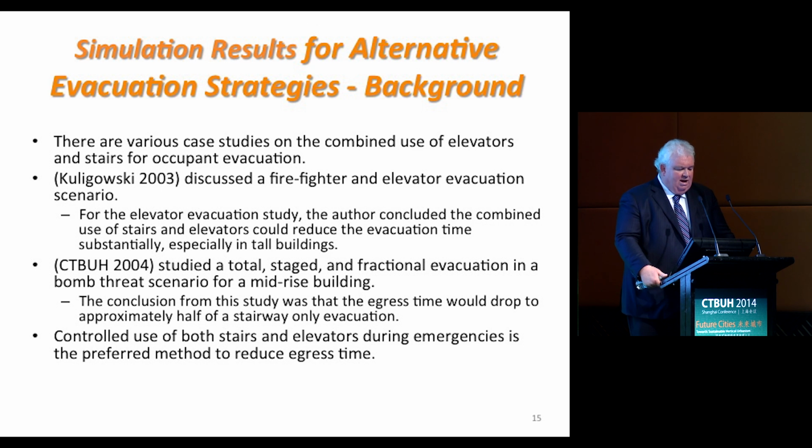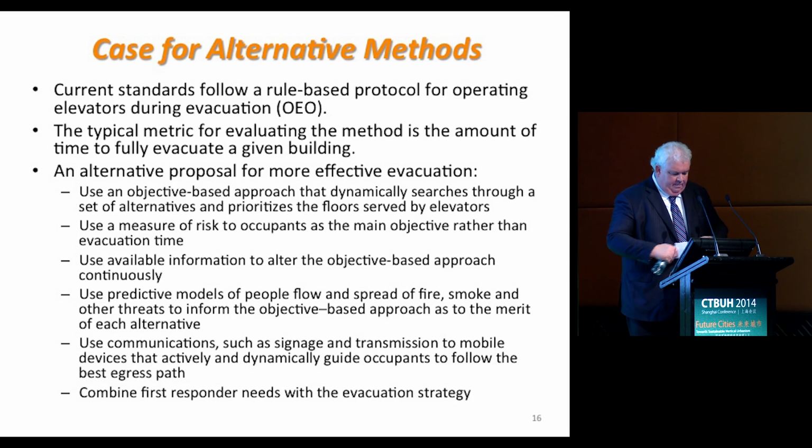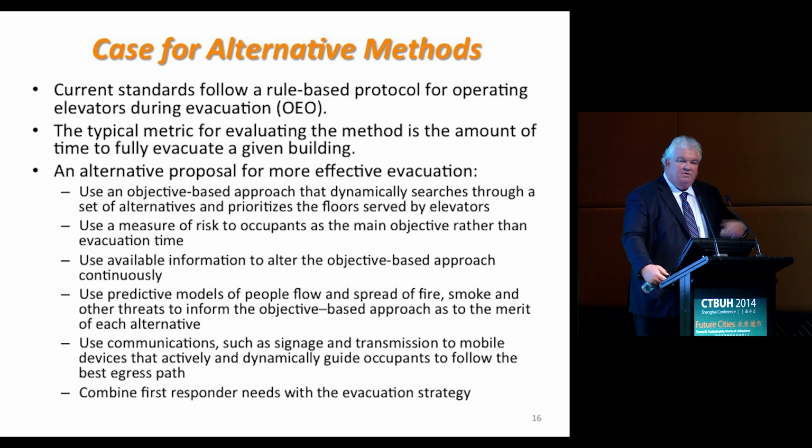Okay, so I'd like to move on now and talk about alternative strategies, which I mentioned initially. Again, I mentioned studies that have been done going back 10 years or more, and these studies have concluded that use of both the stairs and elevators during emergencies is a preferred method to reduce egress time. Current standards follow a rule-based protocol. That's what I've just been through, all of those rules. Even though it's not mandatory, if you do it, you have to do it that way. And those rules were written with the goal of reducing evacuation time.